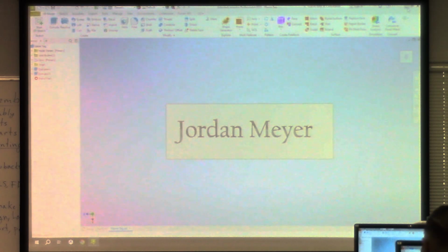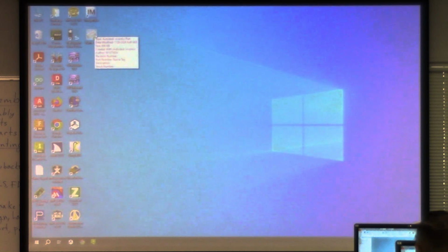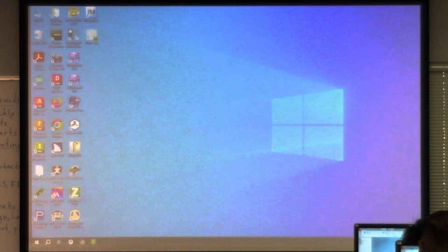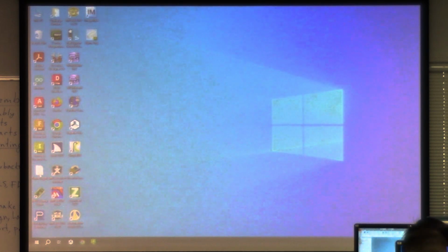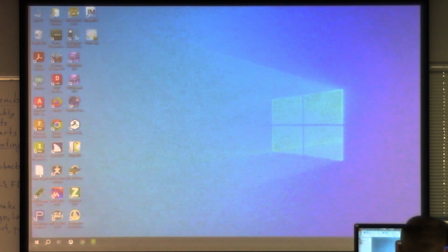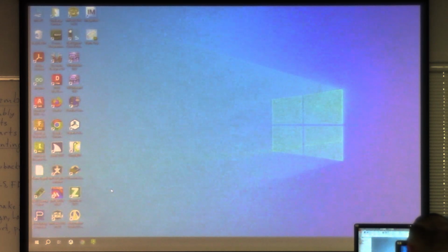So now, if I go to my folder, which is the desktop here, I should see two files. So I've got this name tag part, which is the 3D part that I created in Inventor, but I've also got this name tag.stl. And this is the file that the 3D printer can actually understand. So this is the one that we really need for 3D printing. So when you have this name tag.stl file, that's what we're going to send over to the printer.